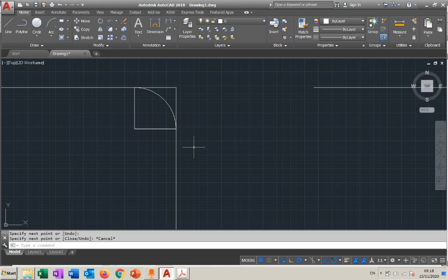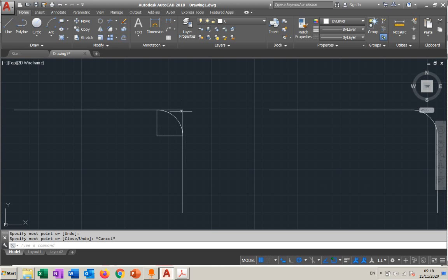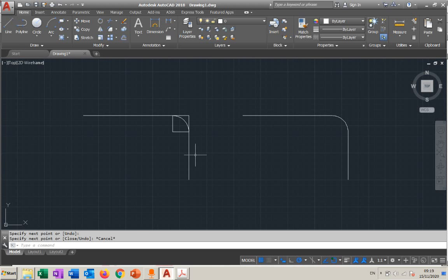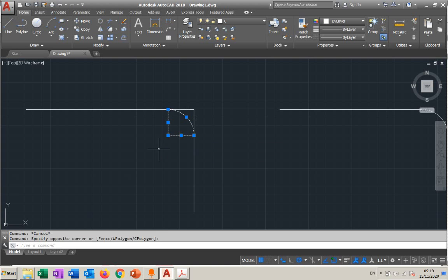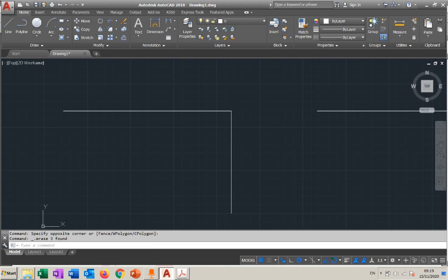I had to do all of these things in order just to make it round. Why? Because if I don't know fillet, I have to do it like this to find its center and use R to do these things for me. So the easy way to do it, we're going to use the fillet command to see how it helps us to do this round corner.